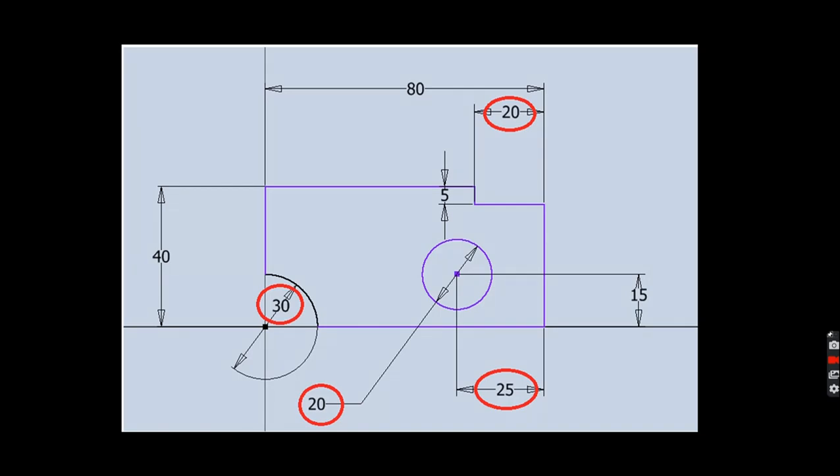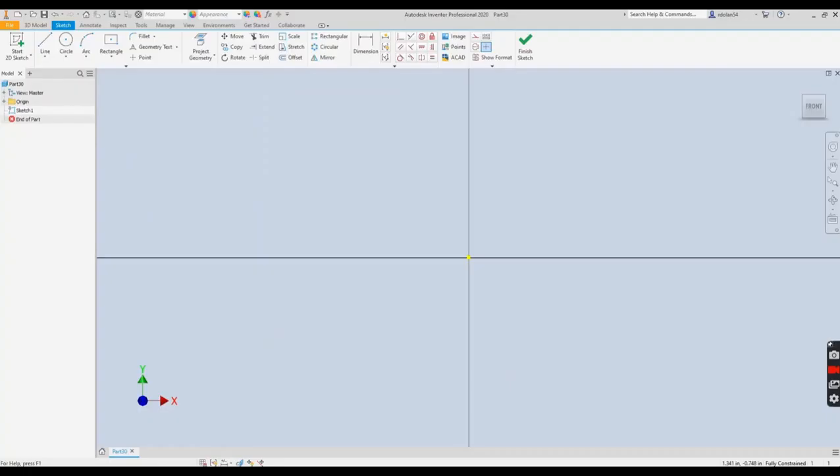and again we'll start with our standard sketch. Here we are back in our drawing, and what I'm going to do is create a rectangle that's 0.375 by 1/4 of an inch, 0.25. I'm going to go to rectangle, 2-point center, and I pick our origin. I'm just going to draw a rectangle. I'll then go into my dimension. I'll make this one 0.375, and I'll make this side 0.25.